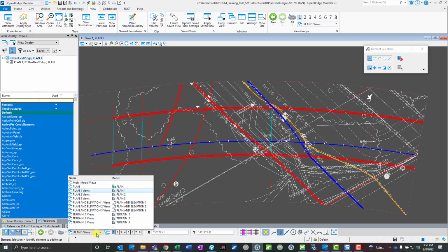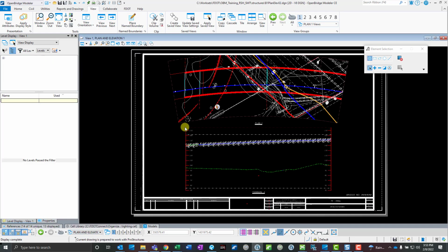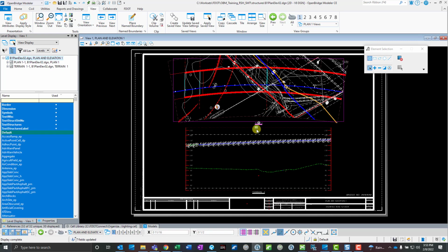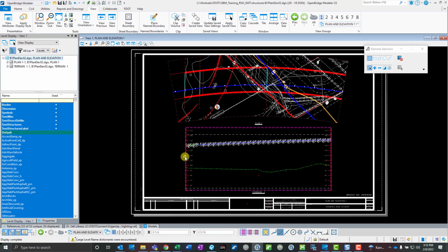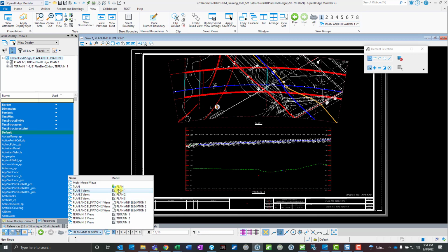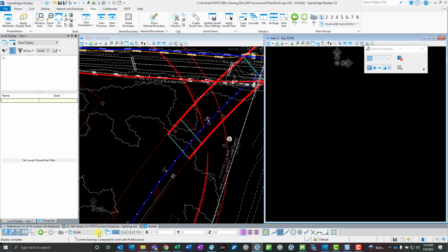And then let's go back to the plan sheet real quick and see what else we want to go ahead in there and fix. Okay, yeah, that's right. We need to go in and fix those name boundaries for the civil profile, right? We need to extend these out. And it should probably be just 25 feet on each side because there's a total of 50-foot overlap, if I remember right. So let's go back to plan view.